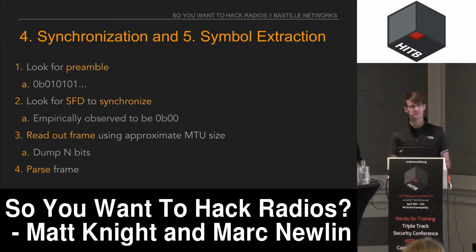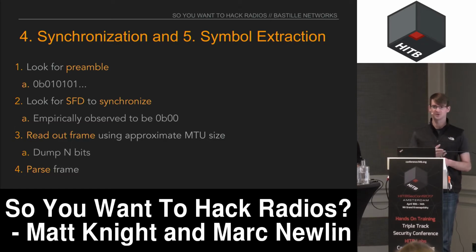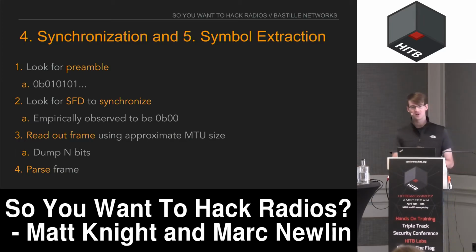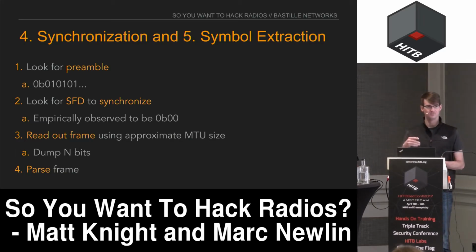And the Python script is actually pretty simple. Really what it's doing is looking at the stream of ones and zeros that are coming in from the GNU Radio flow graph, and it's looking for the preamble. And the preamble is going to be that alternating sequence of one-valued and zero-valued samples, right? Because with FSK, the preamble we expect is going to jump back and forth between the two frequencies, just as we saw in the interactive example.